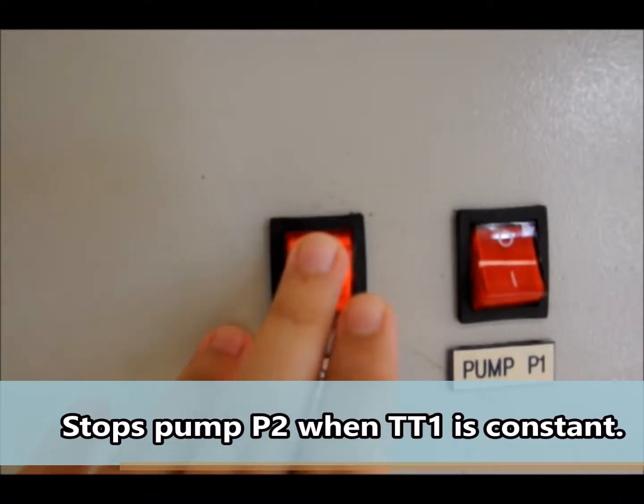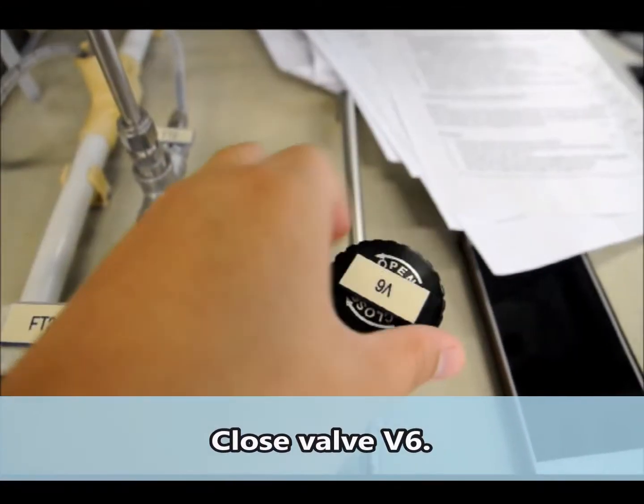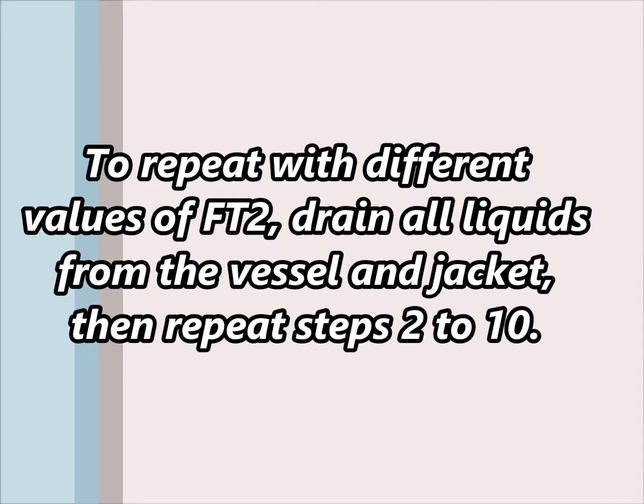Stop pump P2 when TT1 is constant. Close valve V6. To repeat with different values of FT2, drain all liquids from the vessel and jacket, then repeat steps 2 to 10.